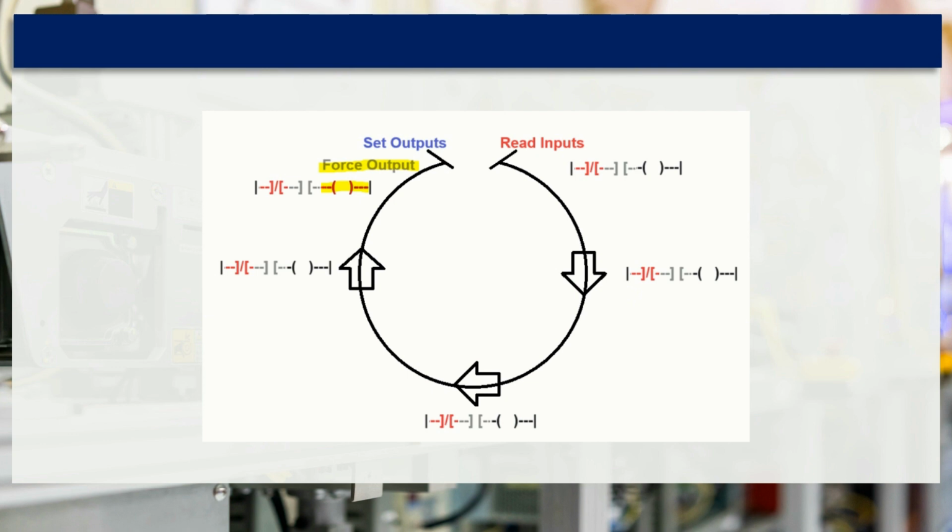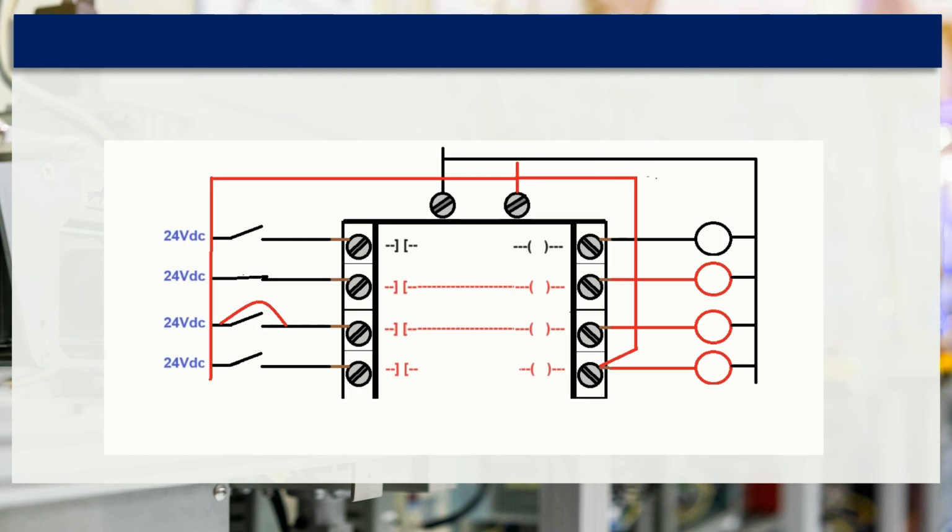To look at this a slightly different way, let's pretend we're looking at the actual physical wires and working in the PLC. So here's my input side, we're feeding it with 24 volts, and this is my output side. The red wires are 24 volts going in, and the return is all on the black. Normally we sink our inputs and source our outputs. So the 24 volts goes to my first switch. My first switch is open, so my contact's not true, I don't resolve the logic, I don't turn on my output. Straightforward.